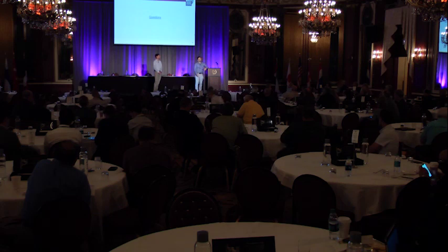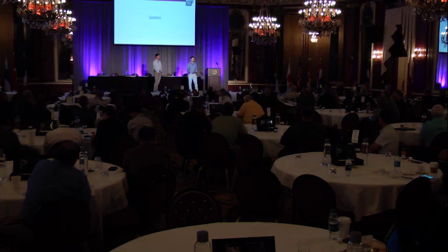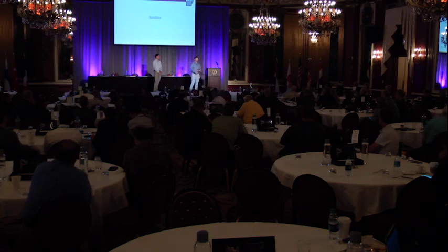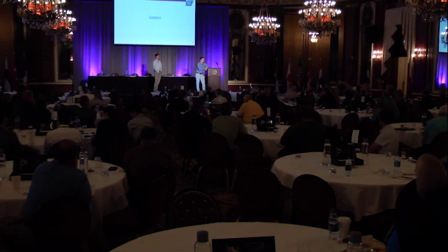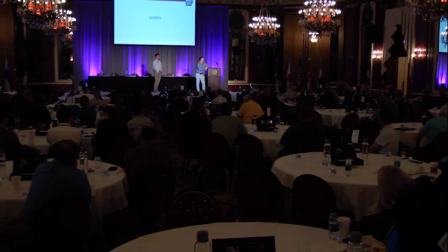Cantilevers can be okay if there's a large backspan. If you have 8 feet of cantilever and you've got 50 feet of back truss, it's probably going to be okay if you're picking it up at a panel point like Mark was saying. But if you've got 8 feet of cantilever and 8 feet of backspan, or something small, then it could be an issue. And that just needs to be talked about up front. There are limitations as well. You also look at exterior wall demolition where you could allow for tie-down cables to prevent uplift on the roofs on your exterior shoring.